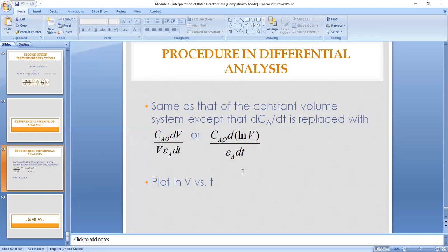So in a constant volume batch reactor, the slope of that tangential line at your chosen concentration would be your dCA/dt, or that would be your rate RA, which you need to get the ln of, together with the ln of the C sub A. That way you can find the rate constant and the order of the reaction, as in our discussion yesterday.